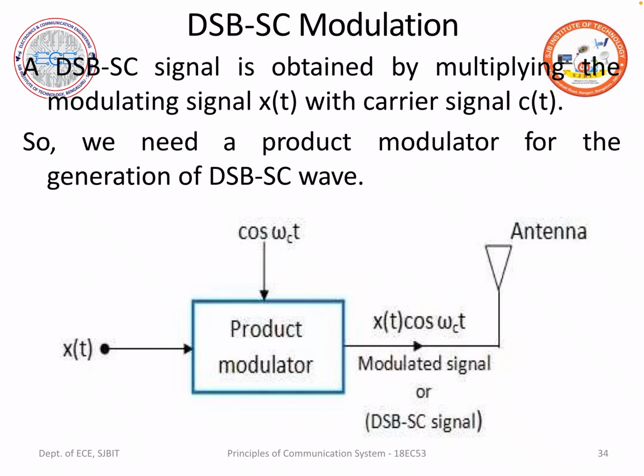When the carrier is amplitude modulated by a single sine wave, the resulting signal consists of 3 frequencies: the carrier frequency and 2 sideband frequencies. Since the carrier is not carrying any information, it can be omitted. That is what we are doing here.